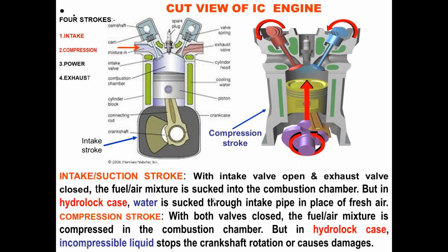The fuel air mixture is sucked into the combustion chamber. This is the combustion chamber. But in a HYDROLOCK case, water is sucked through this. Water is sucked through the intake pipe in place of fresh air. Here is the compression stroke, where you see both valves, exhaust and inlet, are closed, and with both valves closed, the fuel air mixture is compressed.